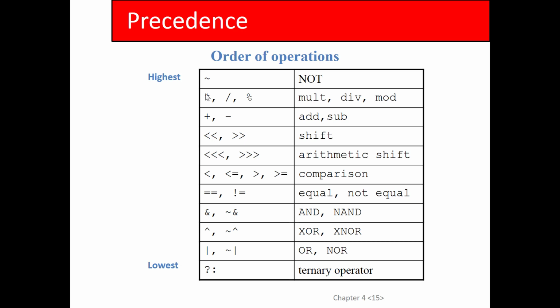Right? But in Verilog, you don't have int and unsigned int. Everything's just logic. So you can get in trouble depending on how you do this comparison. So don't take that for granted. And obviously there's no floating point in Verilog, so you're not doing comparison that way. So be careful with that.